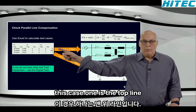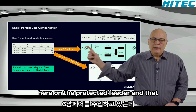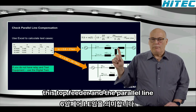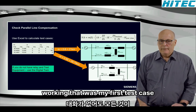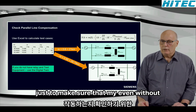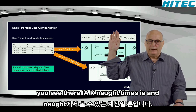Test case 1 is the top line. I'm injecting a current 6 amps over here on the protected feeder, and that would mean it's minus 6 amps IE on this top feeder, and the parallel line current was 0. So that would be the parallel line just out of service, not working. That was my first test case, just to make sure that even without the compensation, everything is working. So it would just be the calculation as you see there, IA plus K naught times IE.